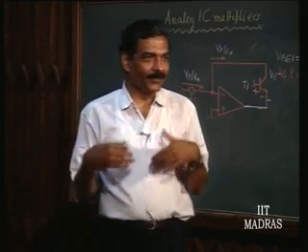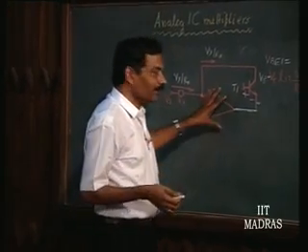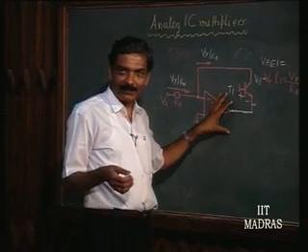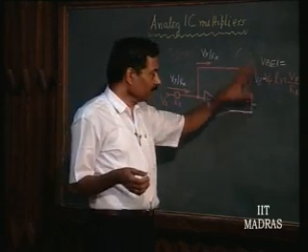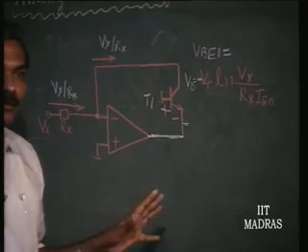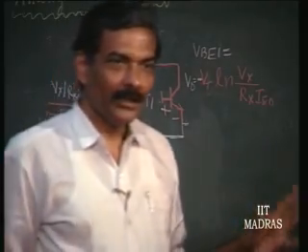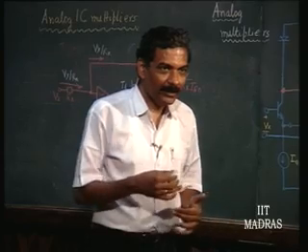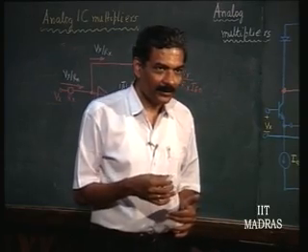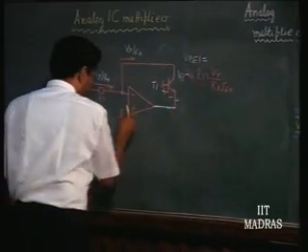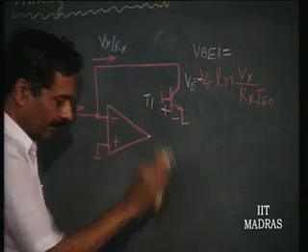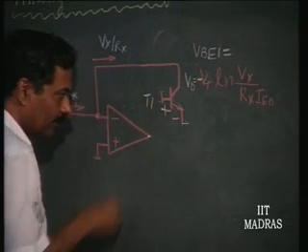We do not want therefore to put some other frequency compensation here, or we would like to use the same old frequency compensation, then this kind of feedback must be given without the gain being increased. So, we put purposely emitter degeneration resistance. So, we will increase the emitter resistance by putting additional resistance here,